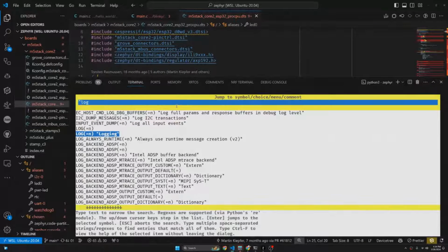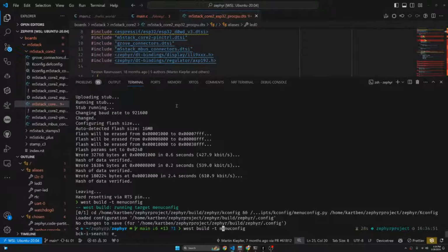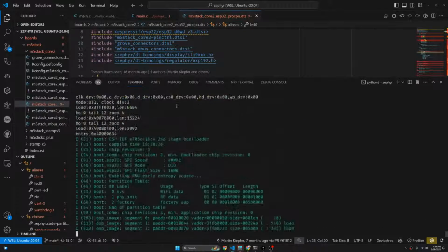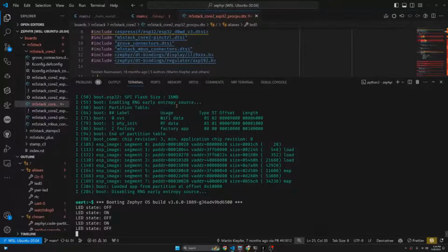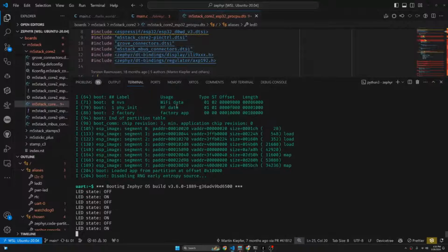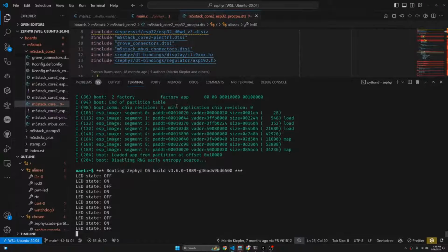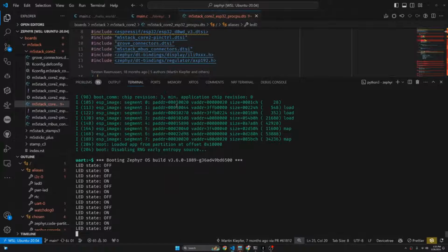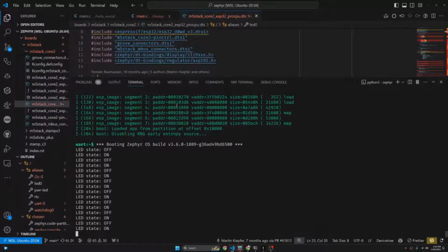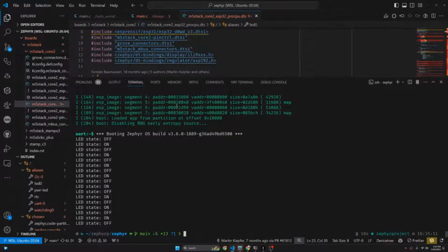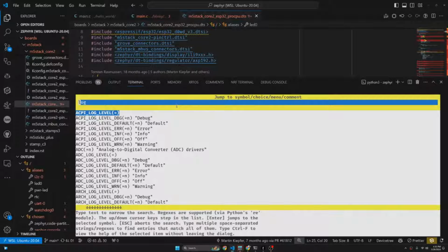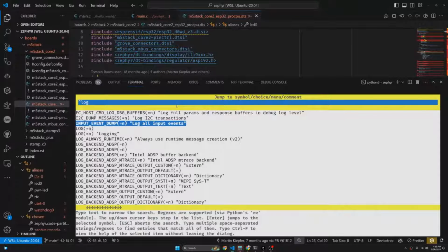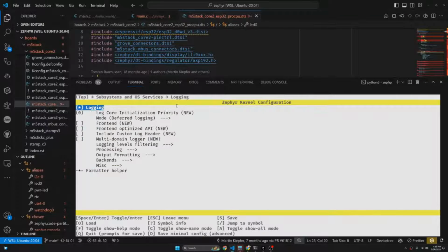Yeah, no, logging is not enabled. If I were to connect to the UART like I did earlier, there are outputs there, but there are no logs. If I want actual debug logs to see what's going on with the GPIO controller, the PMIC controller, etc., I would configure and enable the logs, and I'm actually going to do it because I think that's an important aspect of the demo.